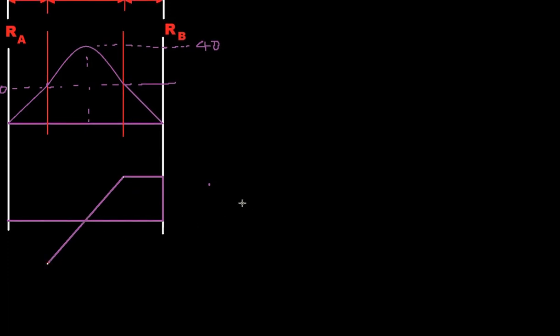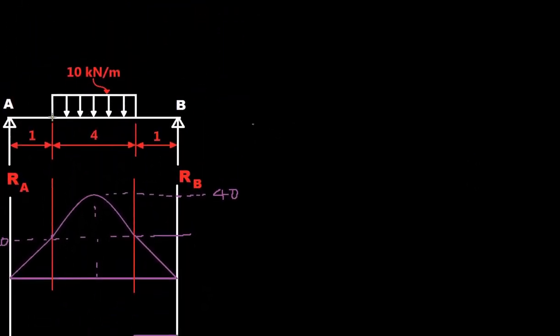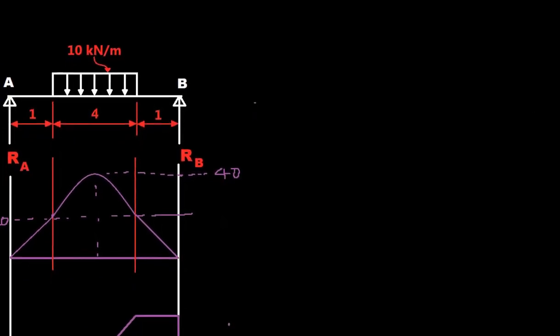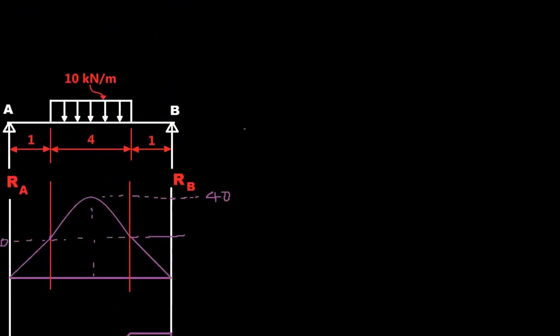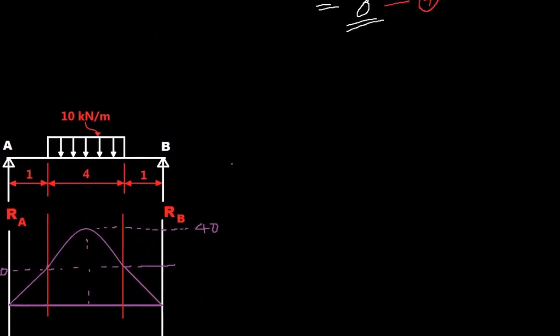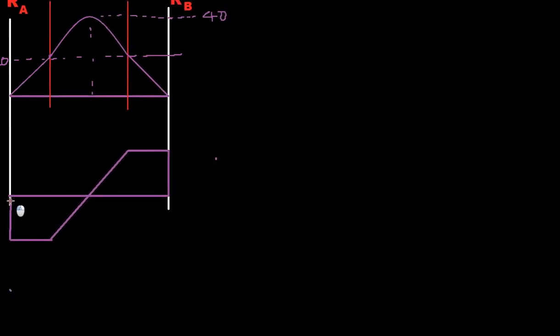So at the halfway mark, it will cross the datum line, and then once it reaches this point, there is no other forces between here and here. Therefore, that load will continue up to here, and then you have your reaction at A, that is 20. So reaction at A will act upward to 20. So this will be your shear force diagram.